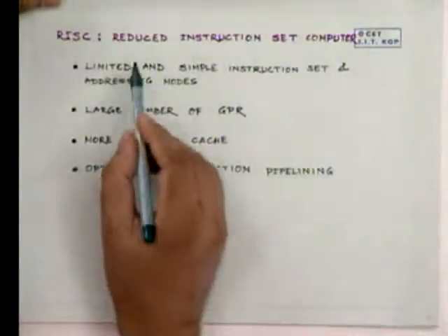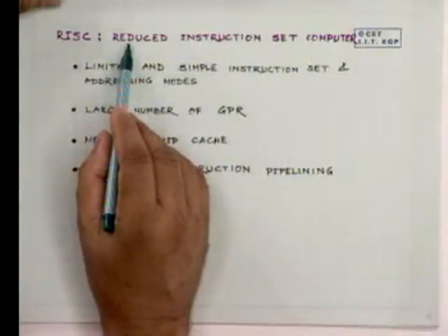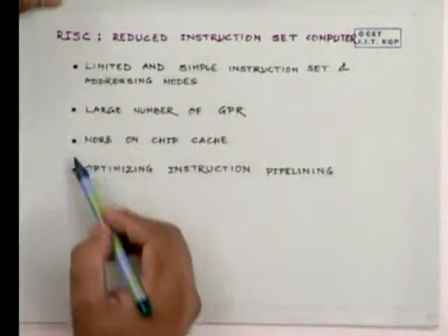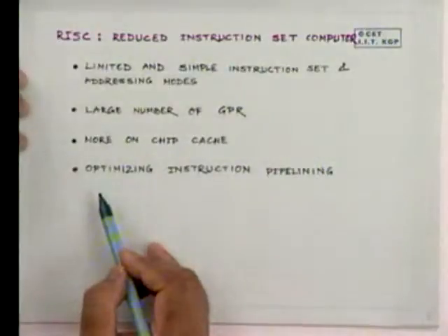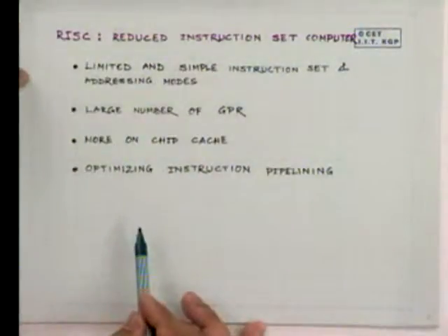One of the important characteristics behind bringing in a reduced instruction set is this: though you can have a very complex instruction set and very powerful instructions, your high level language program has to be converted into machine language automatically by a compiler, and many times the compilers cannot exactly fit a complex instruction to a high level language construct.